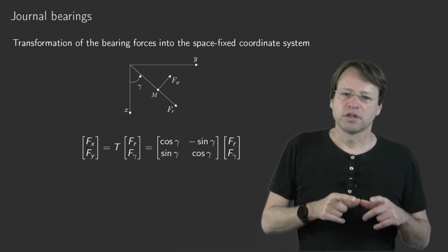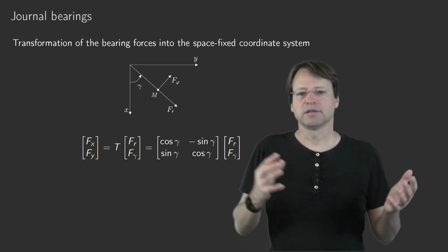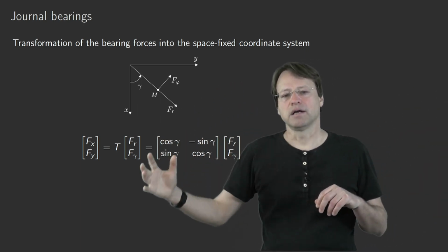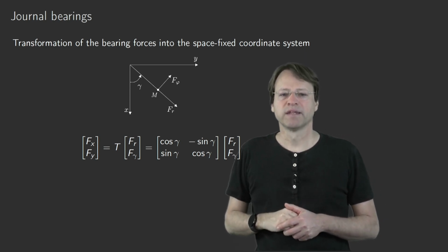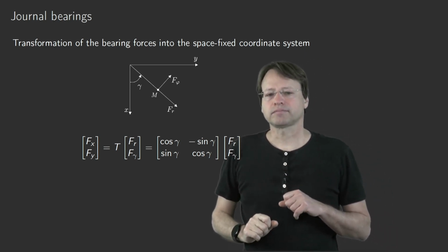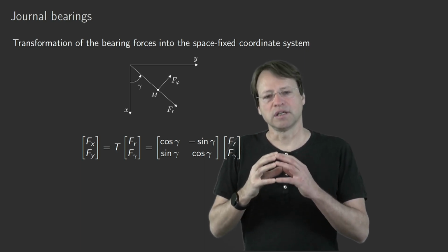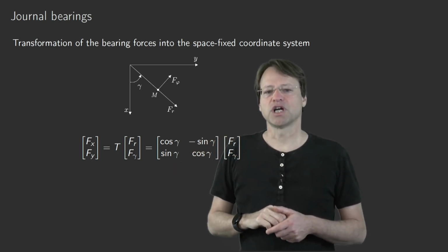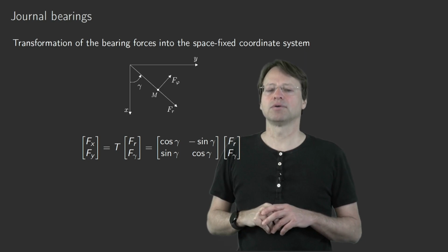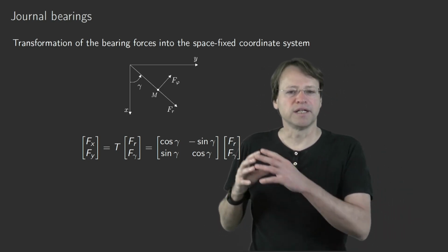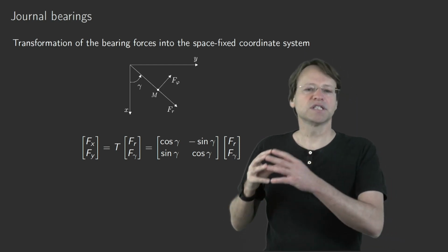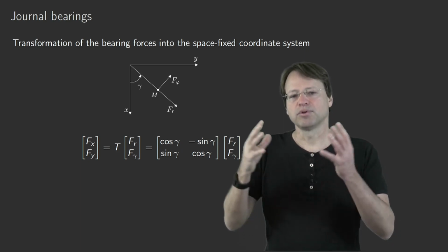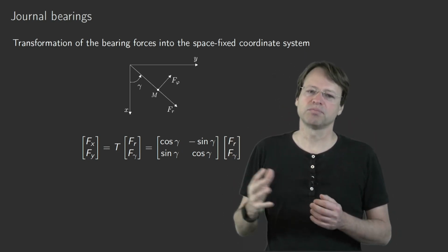However, for analytical purposes, in order to analytically, not by numerical methods, combine a rotordynamic model with a bearing module or bearing subprogram, it would be good to consider static equilibrium conditions, so an equilibrium point for the displacements of the shaft, and then to linearize these forces around that equilibrium position in order to obtain stiffness and damping coefficients. And these stiffness and damping coefficients will then be used for a stability analysis for the computation of critical velocities, critical rotational speeds of the rotor.